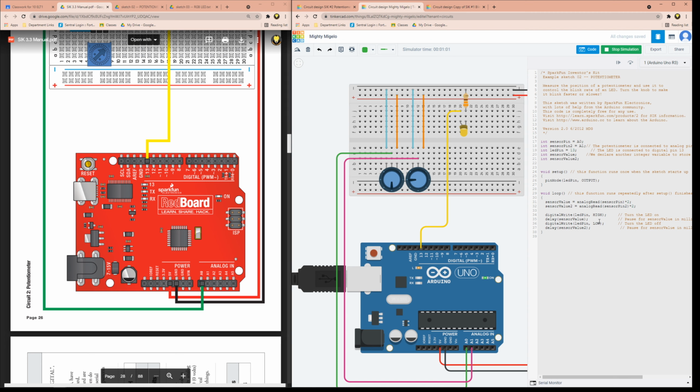When you are writing a variable, you have to make sure you use the exact word that they have, including capitalization. And if you're using the same number multiple times, like LED pin, you should define it as an integer up the top, so you can just use the word LED pin instead of having to look through 13 the whole time.